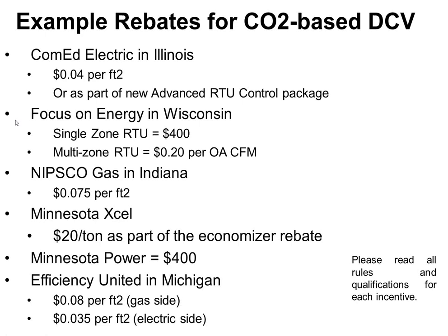So really, to do it correctly, every single zone has to have its own CO2 sensor. Basically, everywhere you decide to put a thermostat, you've defined that to be a zone.